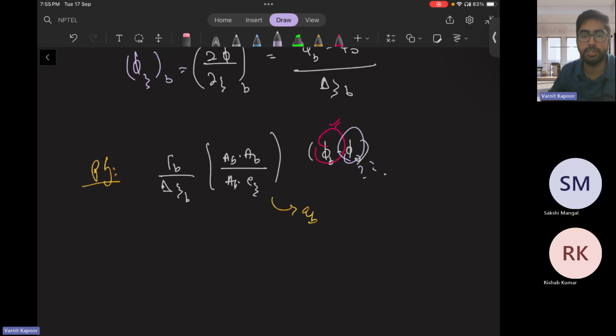If it's a 2D structured mesh, we can somehow calculate phi of the neighboring cells along the tangent. But if it's a 3D unstructured mesh, then we have to do the business of calculating the total values minus subtracting the primary gradient. For structured we used to do that. So for 2D structured or unstructured, it can be calculated using the interpolation. For 3D structured, it can be calculated. For 3D unstructured, we do not have a unique way of defining the two secondary gradients for zeta, eta and psi directions.